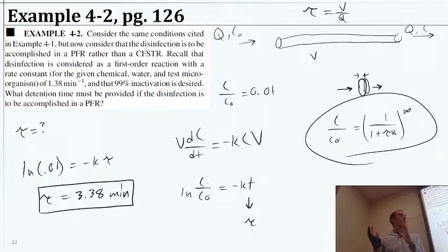Whereas in a batch reactor, you have a lot of time where early on, your net reaction is a large number because there's a lot there. So in the first few minutes, you have a fast rate of change because there's a lot there. Whereas in the CSTR, as soon as it enters the reactor, there's not so much there, and it's only ever changing the amount that's there at that particular rate. So that's a big difference.